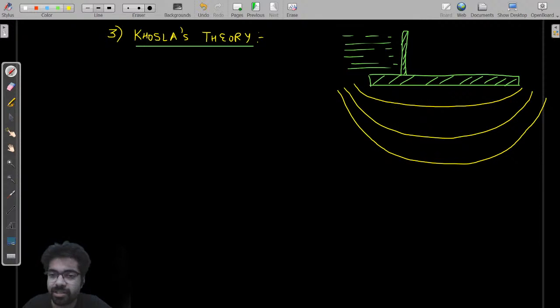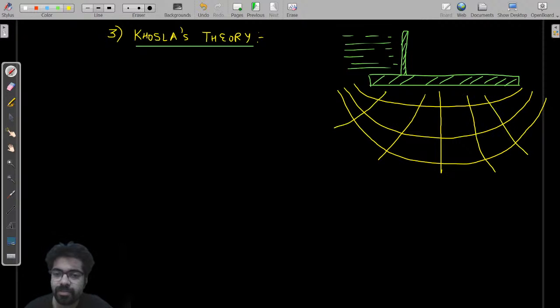So these are your streamlines and these are your potential lines. These lines are your equipotential lines. You all must have heard about it, I guess. So these are your equipotential lines in which head is same. Let me draw some more so that you are more clear. And these are your equipotential. This is your first equipotential line. This is second, third, fourth, fifth, sixth, and seventh. You can say like this last one. So it is like that. And for detail, you can cover this topic in soil.